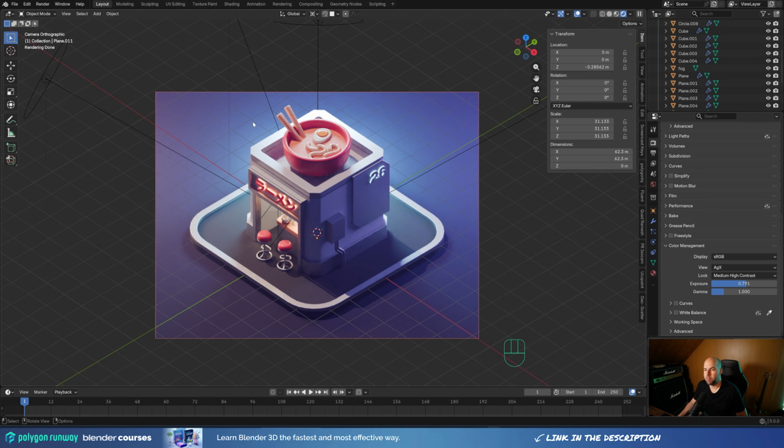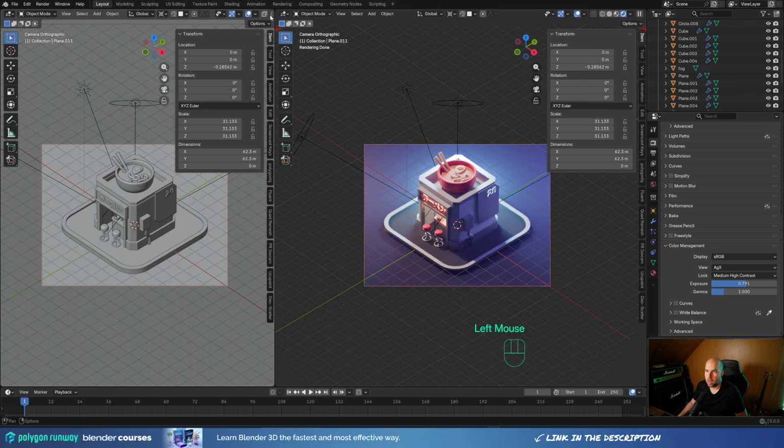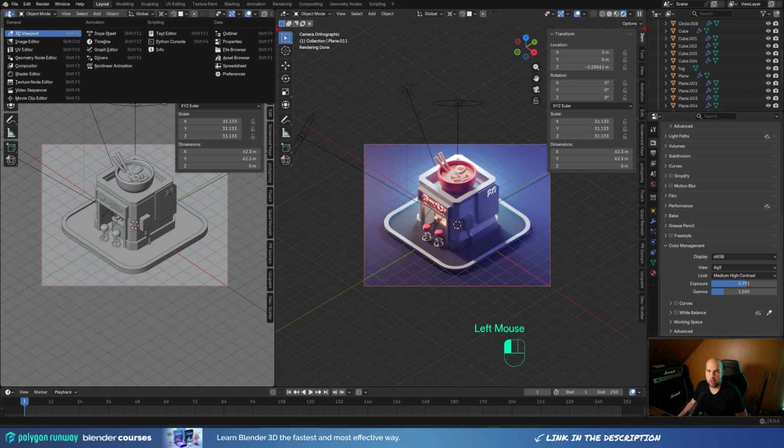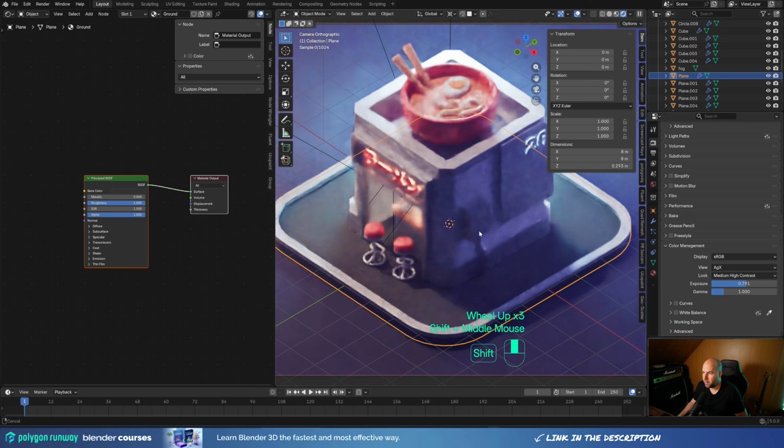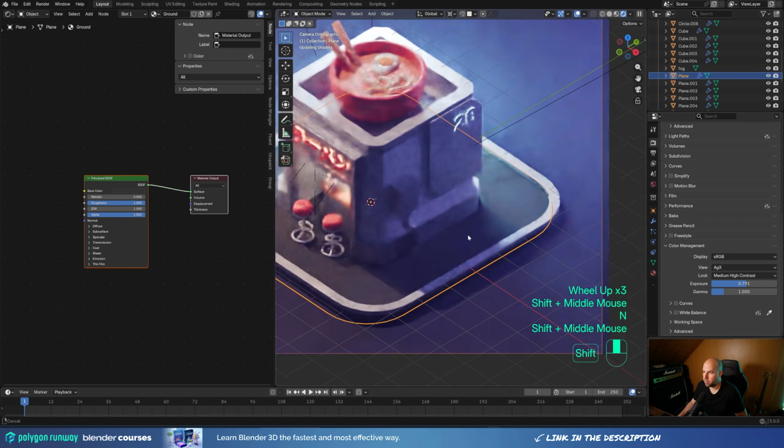But there's one more step you can do to make this instantly better, and that's to add some textures or texture details. So either you can go and find, for example, some concrete textures for the building or for the ground, or you can do some procedural texturing. So with the procedural texturing, I will just grab the new window here and switch this to shader editor, and I will change the ground plane here to something more interesting.